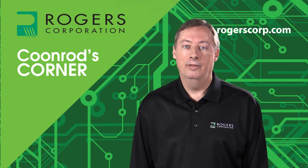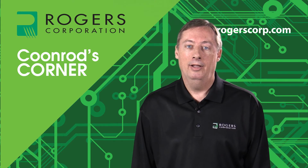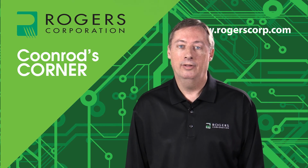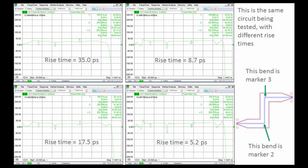So I did a quick study on this using a stripline structure, and the signal plane had an S shape to it, where I had 90-degree bends at two different points. And in those areas, I tested it for impedance, and I was looking at the impedance output using different rise times. So shown here are four different screenshots of the same circuit being tested with different rise times.